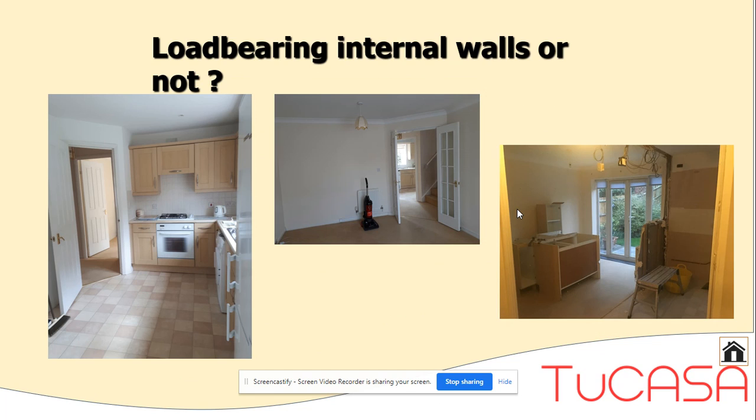Internal walls and partitions, how can you tell if they're load-bearing, part of this load-bearing skeleton structure or not? Well, you could tap a partition wall, and if it sounds hollow, then it's probably a timber frame with the plasterboard on either side, and it may not take a load.